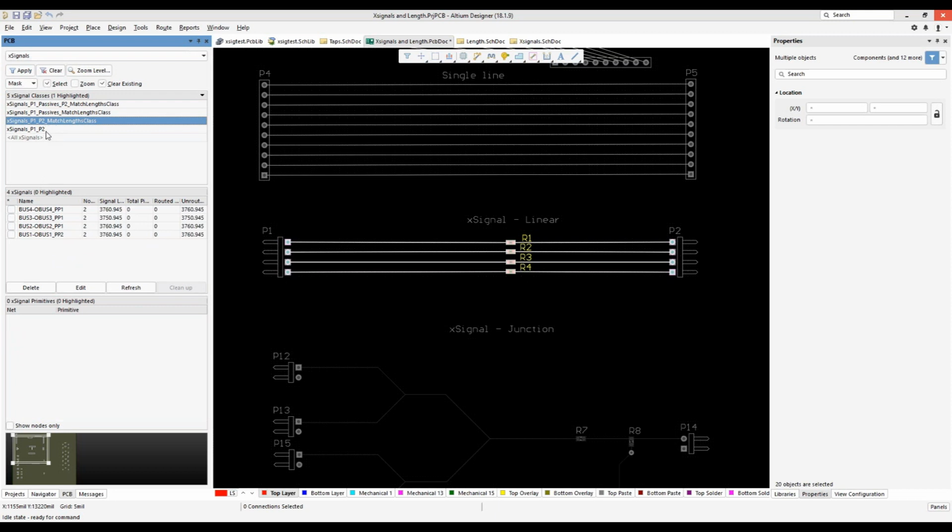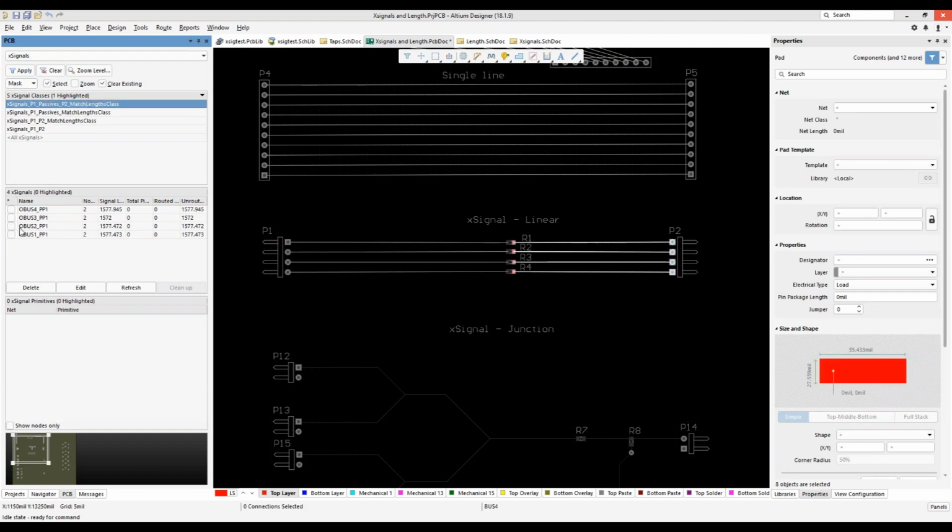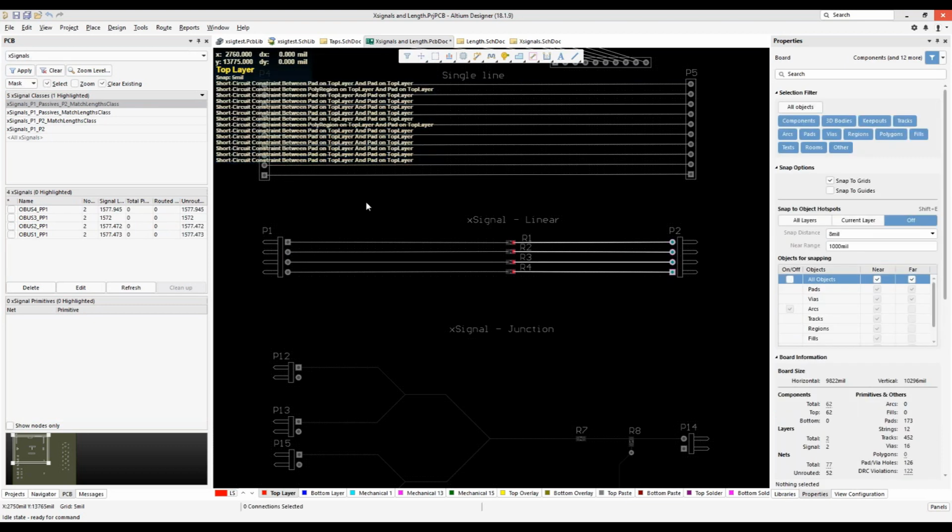So these obviously match up with existing ones. But when you look over here, this was the new rule that was created from the source all the way over to the resistors. And then, of course, if I click on this one here, you can see the names change because it goes from the resistors all the way to the destination. Now, if you do not like what you saw in these rules over here, you will need to close out Altium's PCB doc and don't save it, because if you later on want to delete these things, there's going to be a little bit of a procedure for that, and I'll show you that here in a moment.